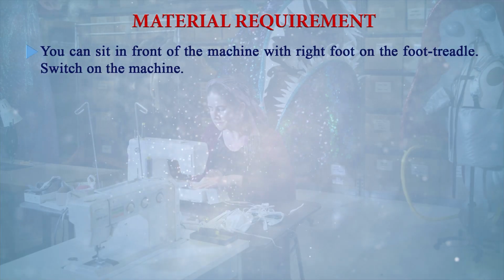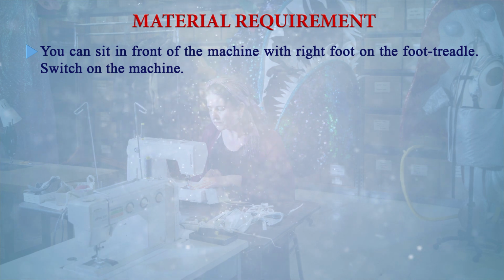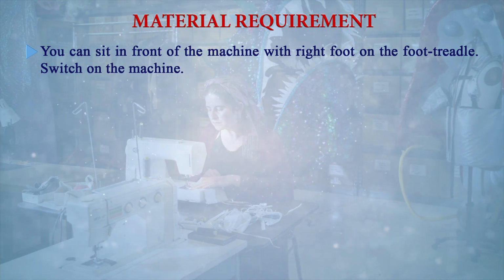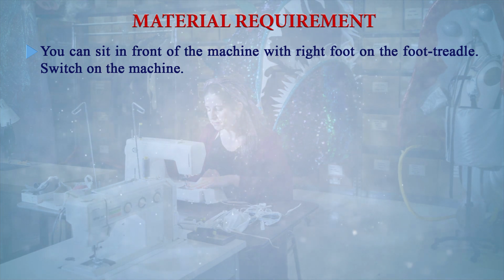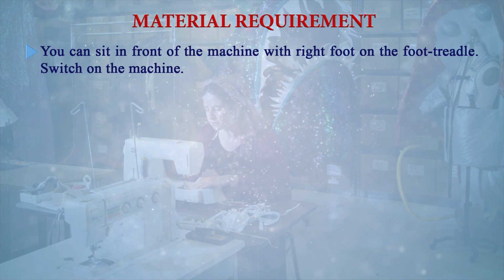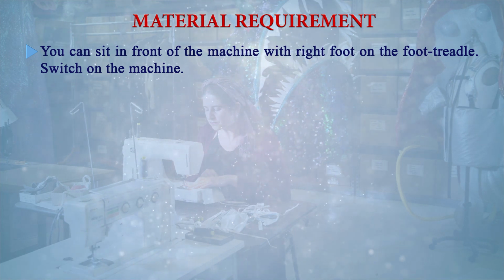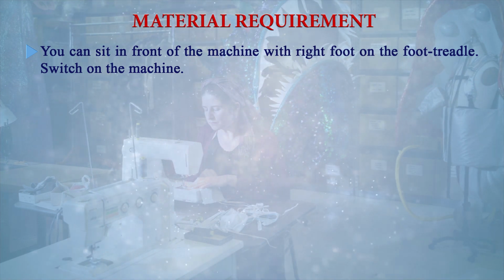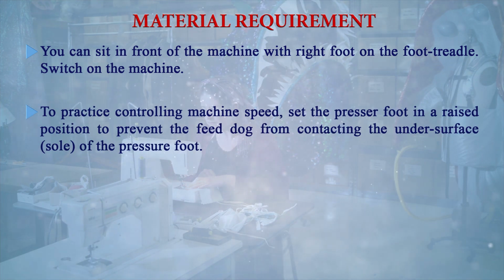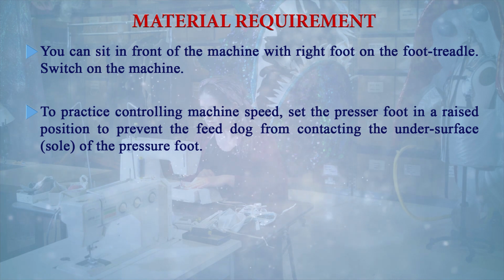Then you can sit in front of the machine with your right foot on the foot treadle and switch on the machine. If you have a treadle machine, which is operated by the foot, you sit in front of the machine with your right foot on the foot treadle, switch on the machine, and then practice controlling the machine speed.